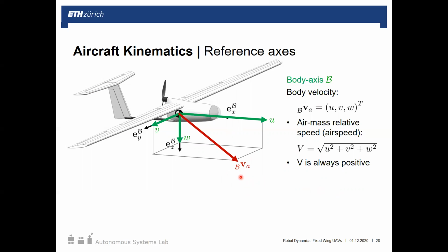And this wind is basically, we're assuming that that air mass itself is moving, and that's what the effective wind is. So that's why we need to really distinguish A, for airspeed, this is relative to the air mass in which we're flying. So V capital is just the magnitude of our airspeed, and we'll assume it's always positive. Then we get body rates.